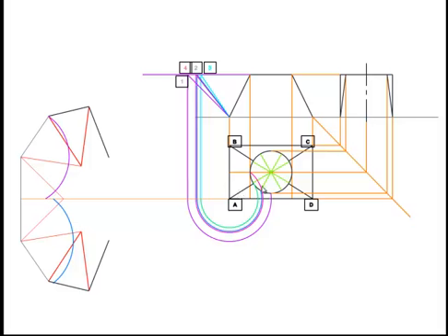Now we need to find the distance between two of these green sectional cuts and step it off from our apex here. This will locate this point where the blue line comes in contact with the circle in plan, like so.